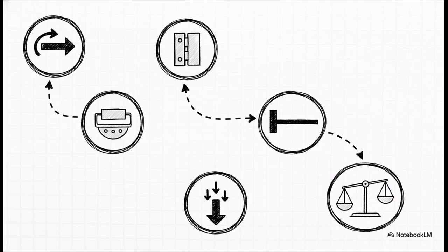Let's do a quick recap of the anatomy before we wrap things up. To be a successful civil engineer, you absolutely must conceptually manage translation and rotation. You must correctly identify your joint. Is it a roller, a hinge, or is it completely fixed? You must know your bone. Are you dealing with a cantilever or maybe a continuous beam? You need to neatly convert your stressors, turning those UDLs and UVLs into clean point loads. And finally, map it all out visually to find mathematical equilibrium. Boom, you now have the full conceptual roadmap perfectly mapped out.